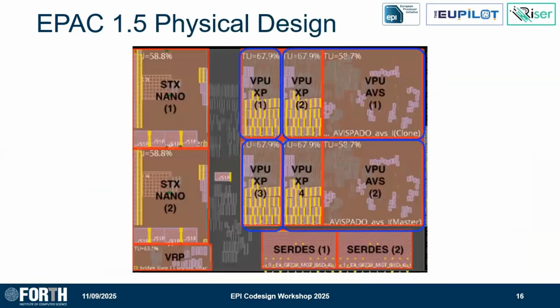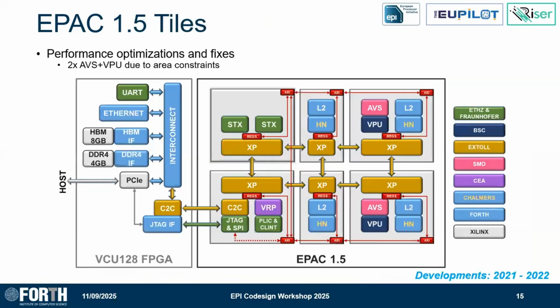And then the cores get a little bit fatter in terms of area, and we have a specific area budget, so now we have to decide what to leave out. And what has happened is we left out 2 cores. So the rest of the memory hierarchy was the same, but now this chip had just 2 cores and GPUs instead of 4 in the previous version.